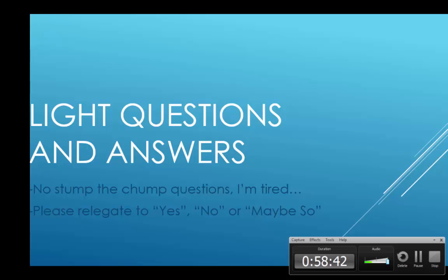I will say that the next presentation was a little bit of a struggle. I'm not a big fan of configurations at assembly levels, except for very, very light stuff, like opening panels or moving a robot arm or something, showing different positions. Switching things out just seems like a real big compound coming together. I do talk about it in the next session, but I'm not a big fan of it at that time either. But yeah, that's about it. Just don't try to control parts. Control configurations of parts. Don't control the part directly. It's never going to work. You think it works, it doesn't work.